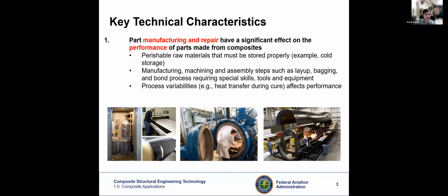First of all, when we are making an aerospace composite part, we start with raw material. These are quite formable materials at the beginning when they're in an uncured state. For this course, we're talking about thermosets such as epoxy composites. So you have to store them in a freezer at very low temperatures. Then you have to use them to lay down your laminates. You vacuum bag them, you place them inside an autoclave, you cure them, and then you have your final shape and geometry. So unlike other types of material like metals, you're creating the structure to net shape.